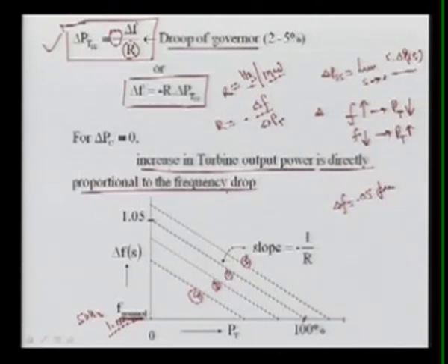So this gives that if you are loading 100%, and your frequency is rated at 50 hertz, then there will be a change of 5%. Meaning now the load is reduced to 0. The change in the frequency here is 0.05 multiplied by 50, meaning there will be a change of 2.5 hertz in the frequency. So we have the family of curves. Again they are having the slopes.